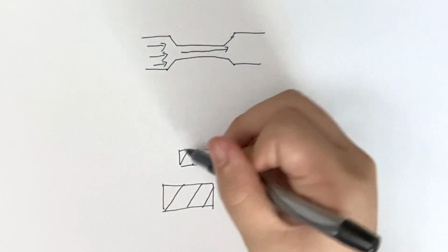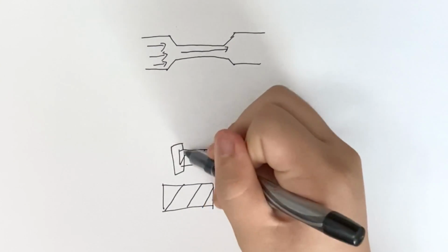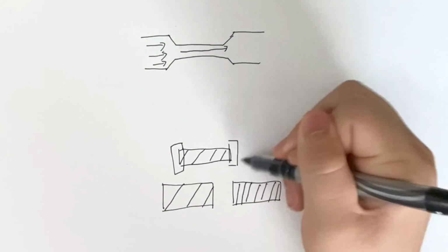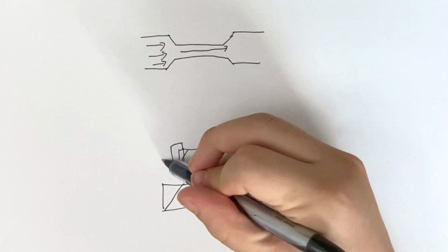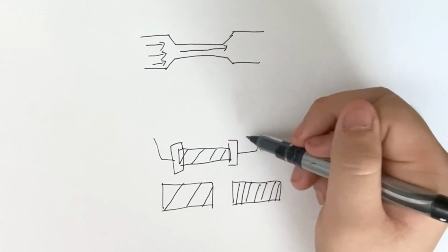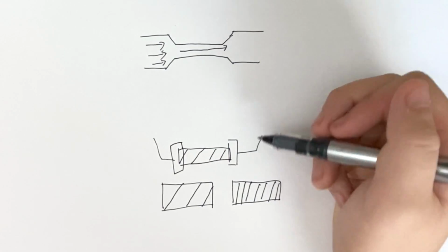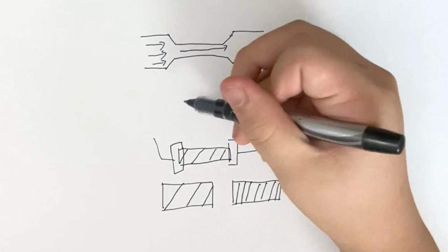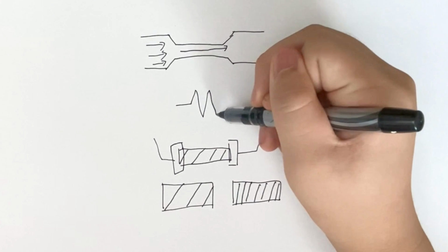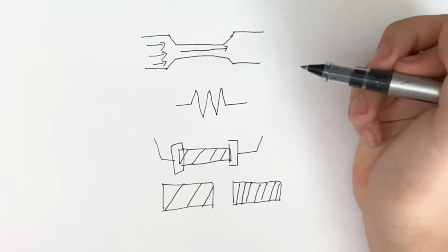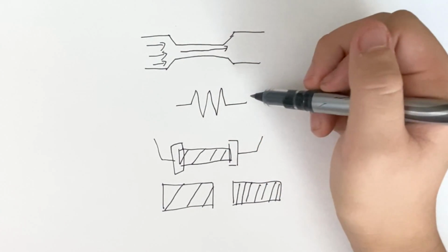After that, they put caps on the ends with leads on it. Then they dip this middle part into a lacquer coating, which is how a resistor is made. By the way, the symbol for resistor is this. It looks like a zigzag with leads.